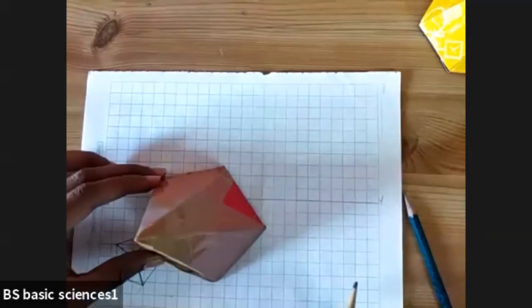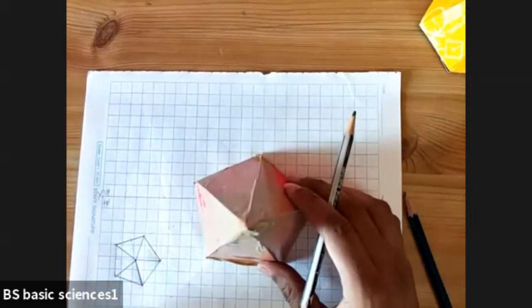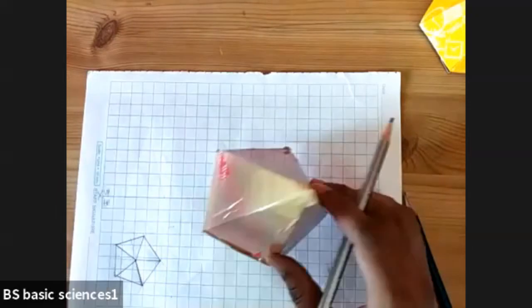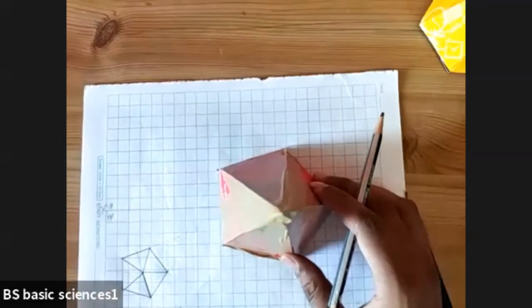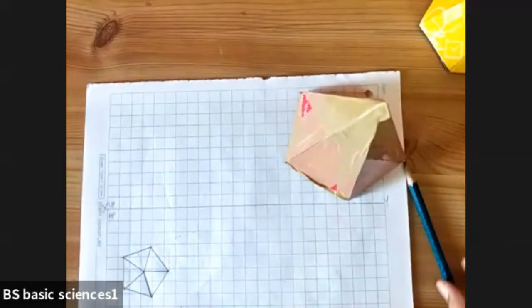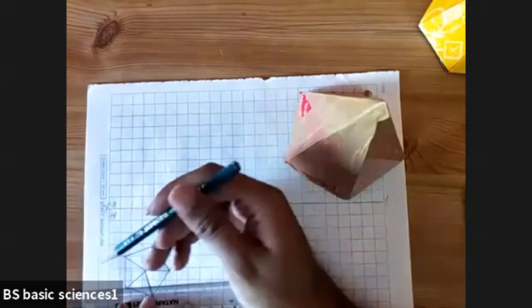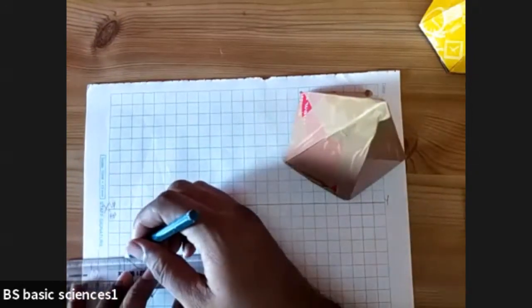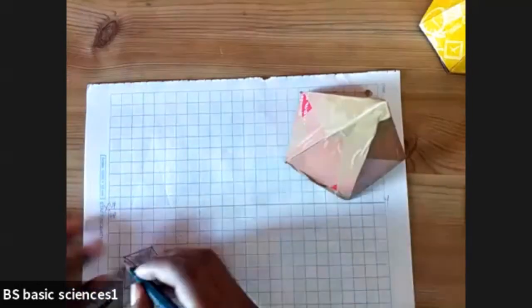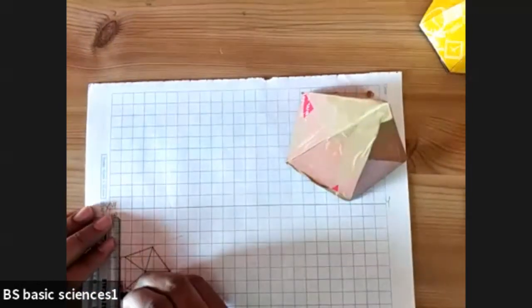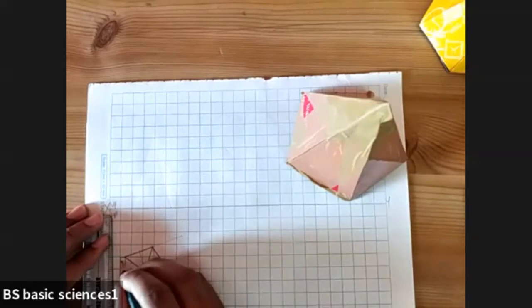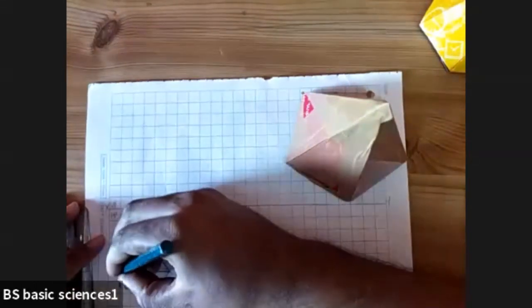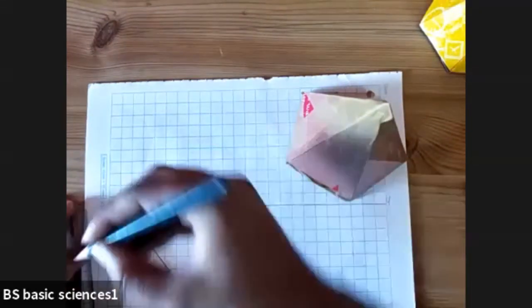Okay, a pentagon pyramid is placed on HP with respect to one of the edges. Okay, that is what we have drawn. The top view is done. Show the dimensions. What is the length of the side? The side length he has given you is 25. So mark this as 25.